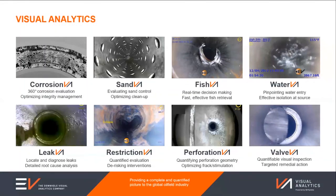Okay, Mike, any other questions? I think I did see one that just came in. Is this camera running cased hole only? I think for the most part, by the nature of the operations that we do, it is predominantly cased hole, but we have had some applications in open hole environments, and in some cases looking particularly at fracture networks and what may be coming through them. There are two particular circumstances I can remember. There was one where we were looking at fractures in an open hole and looking at where water was coming from. So very relevant to this discussion. And we've got some great images of that, showing the water coming in through the rock directly at source.